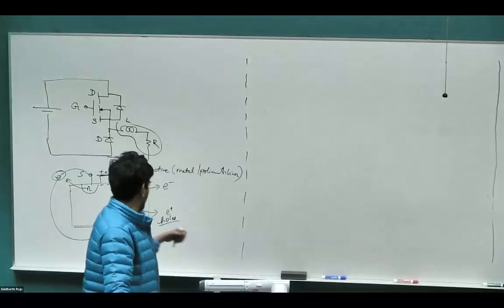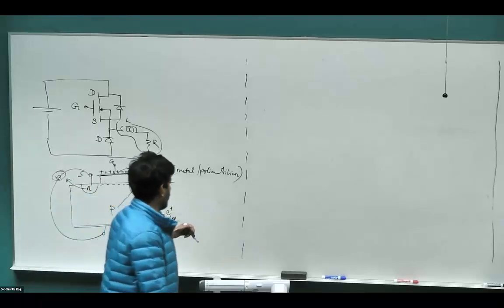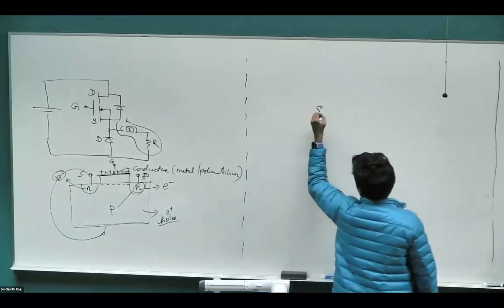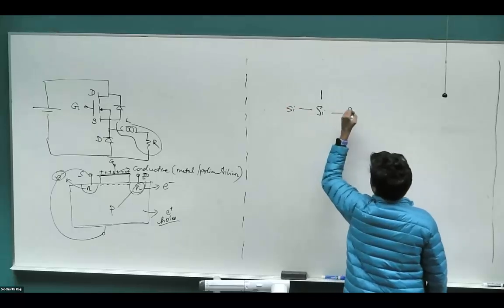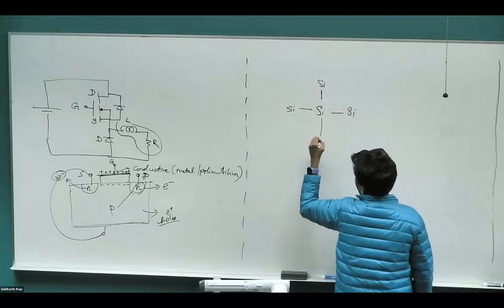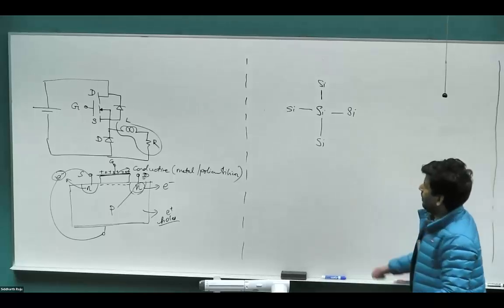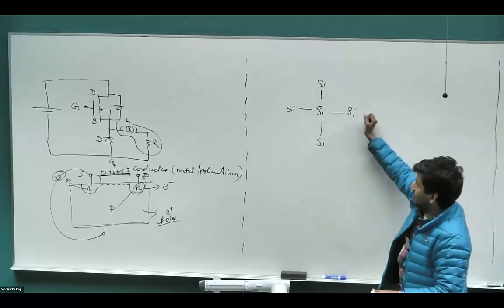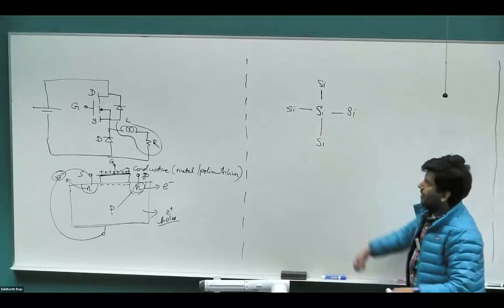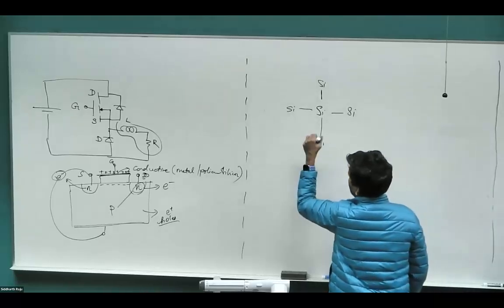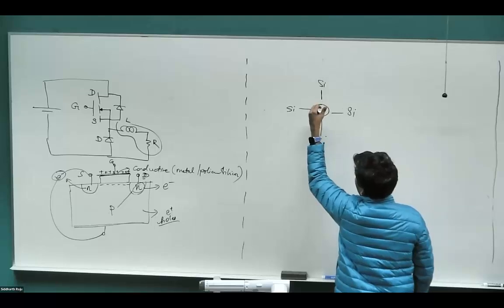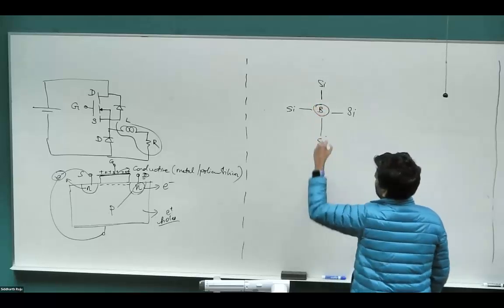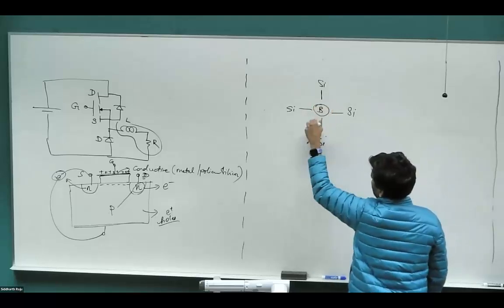Yep. Typically you would have a silicon substrate with boron infused into it. So when you have a silicon lattice, it needs 4 more electrons to make a stable orbit. So it will basically form this crystalline lattice with 4 other silicon atoms. But what you would do is infuse like 1 in a million part of boron every now and then. And this requires only 3 to complete.